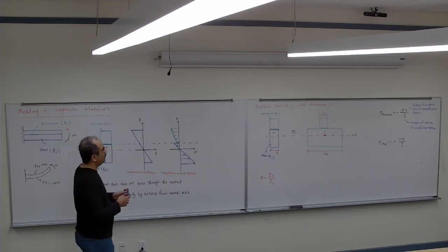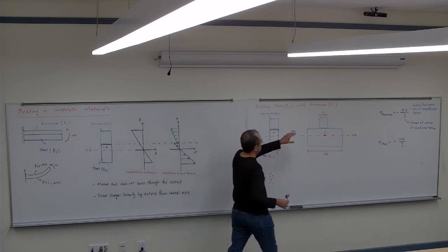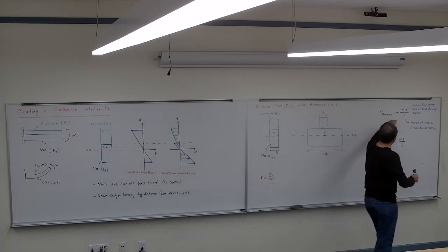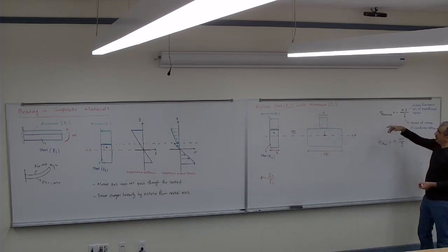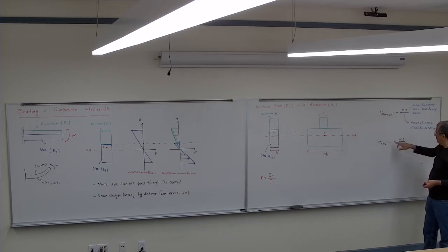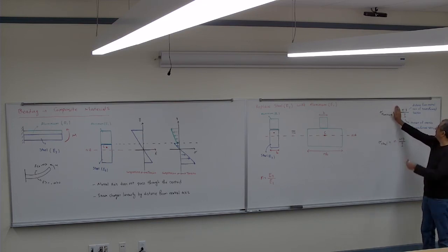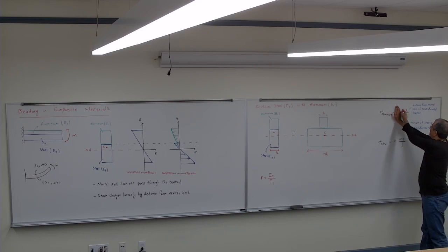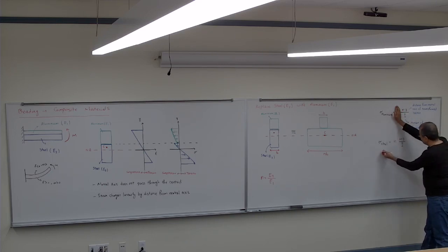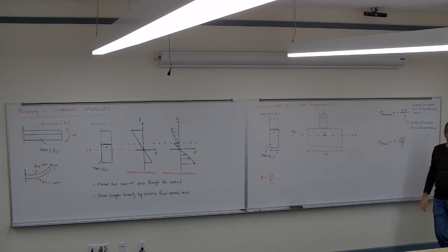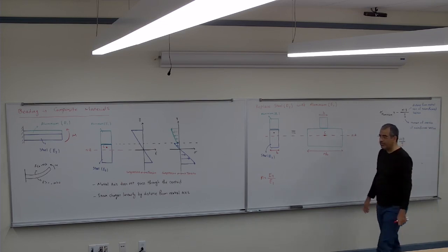So in the part that I didn't mess with, just the original equation that I have. The negative because it's in compression. It's going to be positive because of the tension. So the negative, positive depend on which way you are bending it. So the original equation is My/I. So the original section My/I, in the section that transformed is going to be n My/I, multiplied by n.